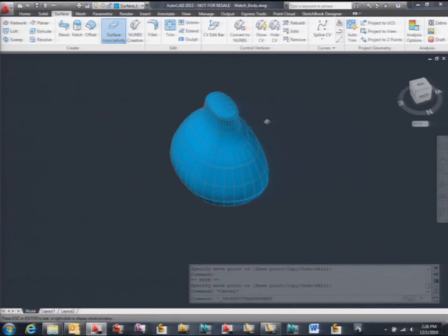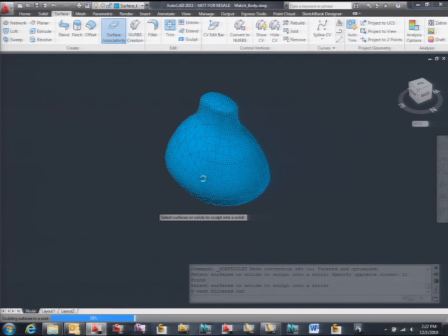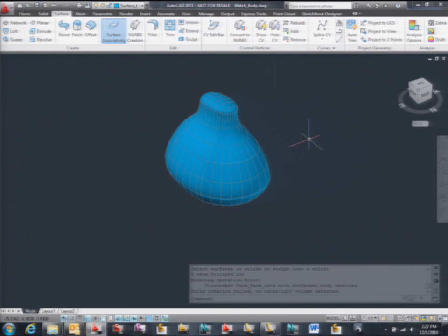So now I can use a command called Sculpt, and Sculpt will get most enclosures of space, right? Convert that into a solid. So anything that AutoCAD believes to understand is watertight, and it closes space, that will become a solid. Sometimes it can get tricky. In G2 continuity, sometimes it feels like it's fine, but it may not be exactly fine after some tweakings. At those times it may fail, but normally this will create a solid. That's it. It's already just a solid, and then you can work with it.